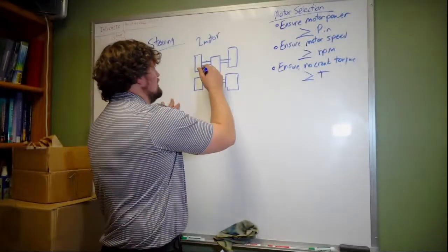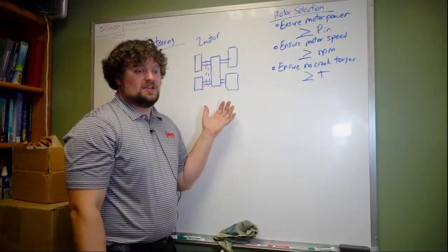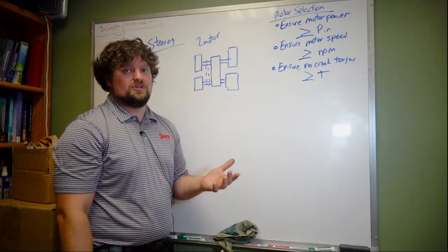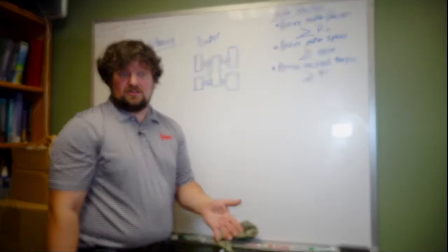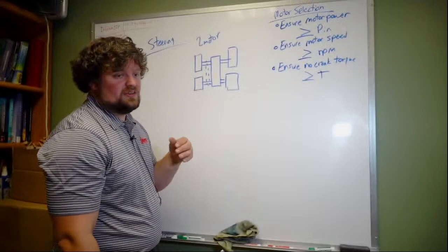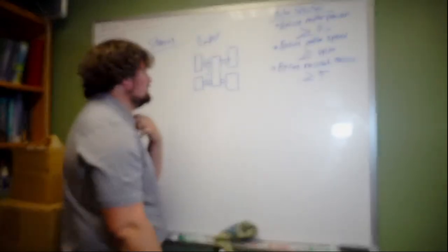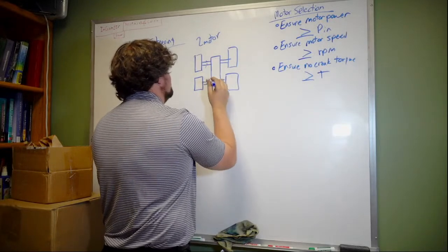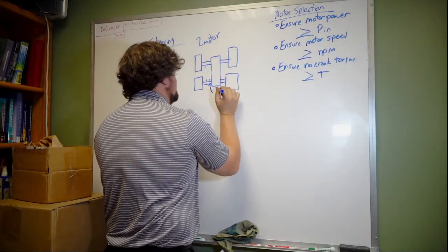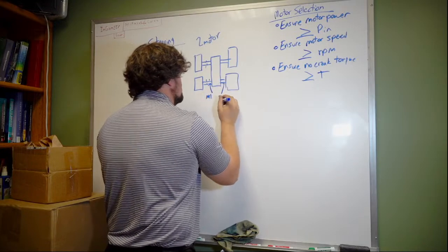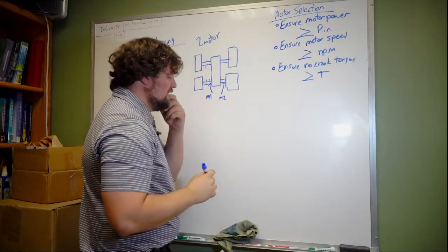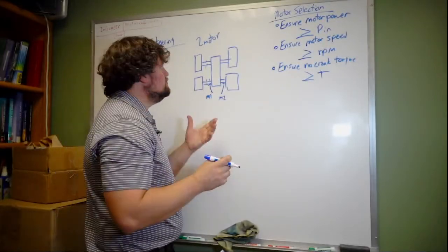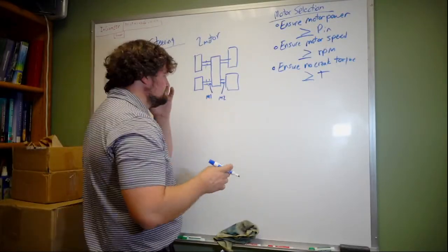Okay, so you can connect those two axles. Typically, again, I would say that's only for an off-road vehicle. You're not going to want to have four-wheel drive on a race car, or even on just a regular moving vehicle. So what you'll have is a motor, which is connected to gearing, connected to this axle. It's motor 1 and motor 2. Okay. So let me talk about how to steer in a two-motor system.